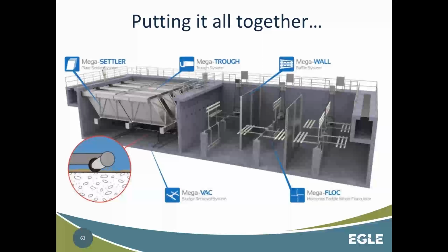Typically the plates are all stainless steel, and it's kind of neat when you see the design because it's really about the projected area of the plates, and that's how they're able to reduce the footprint, based on the surface area of the plates that's being exposed to the flow direction. But very interesting. Fortunate enough to see several of these plants, and who knows, maybe we'll see more of the clarifier plants that are struggling with thermal upsets moving in a direction similar to these plate settlers, because in a lot of ways they provide the same advantage as the clarifier in the reduced footprint of the facility.